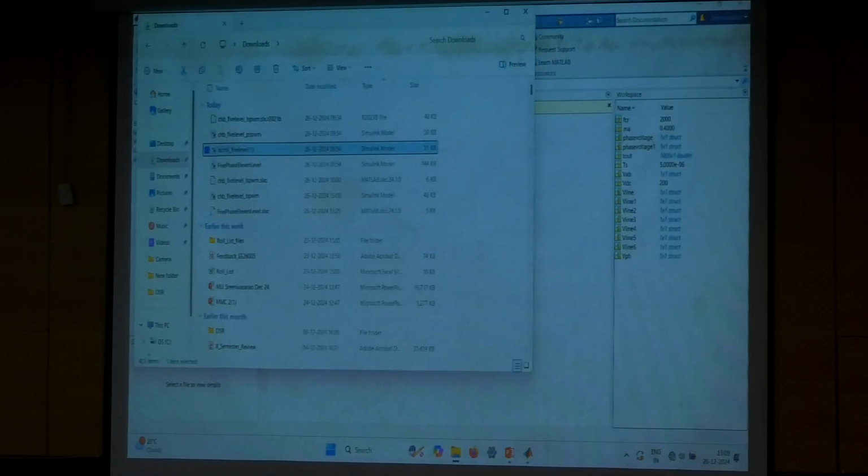So what is your suggestion if you want to control: is SPWM okay or SVM okay for a multi-level inverter? SVM is fine maybe up to five levels. Beyond that we have to use other methods or nearest level control. For a 5-level case you will get 125 switching states, and beyond that you will get more and more. It is not easy to select a particular state, so you need a lot of optimization and calculation, and methods like model predictive control or some optimization techniques.